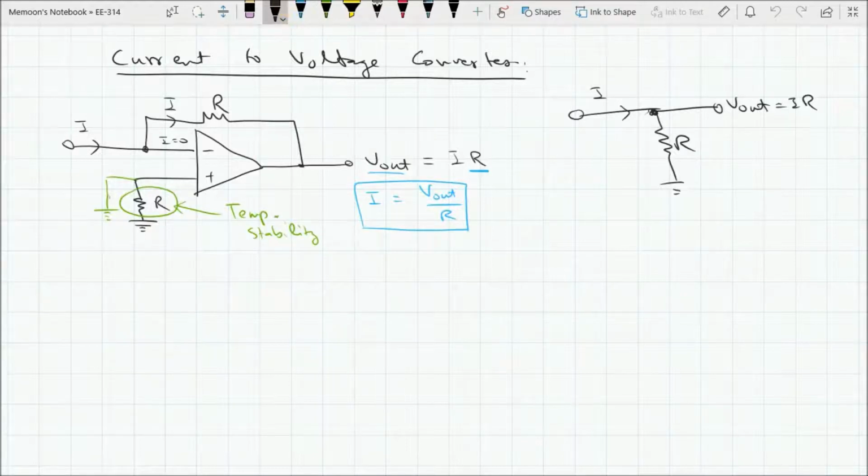So it can provide voltage or current to any other third stage system, and that system will be unable to load this op-amp's output unless and until the V saturation or I saturation of this op-amp, its physical limitations, are reached.